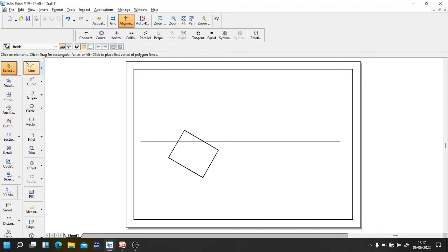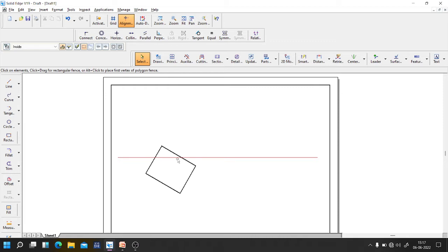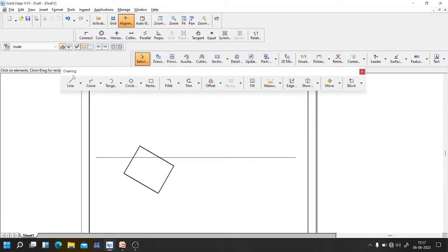Okay, so now I need to move here. I'll just move it. Okay, so use the move command and bring it down. It is not above the XY line now. So now just bring this one on the down side. So here it is a move command. Now to select the objects you can place a window selecting from left side to right side or right side to left side. Okay, now let us specify some reference point, then you move.